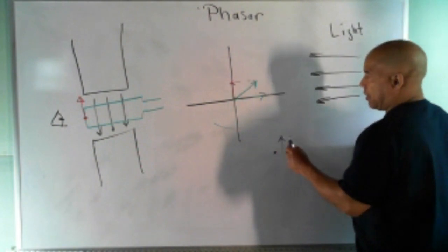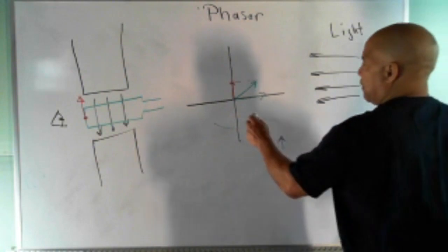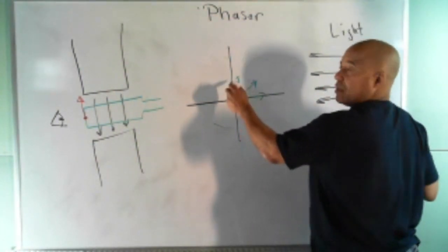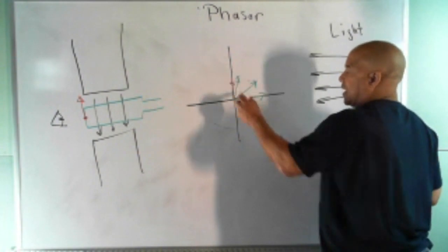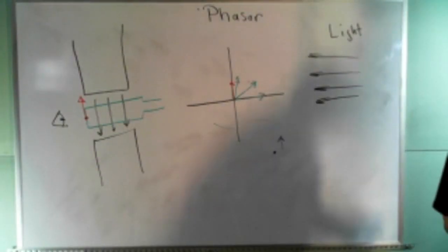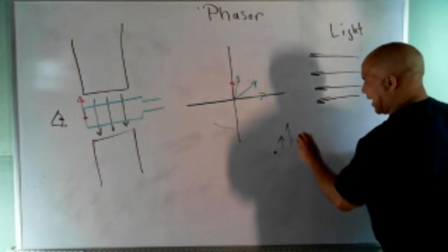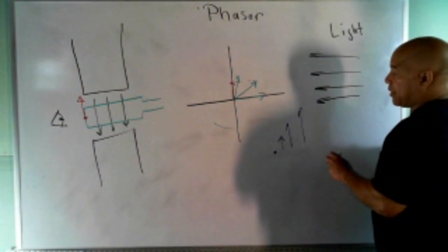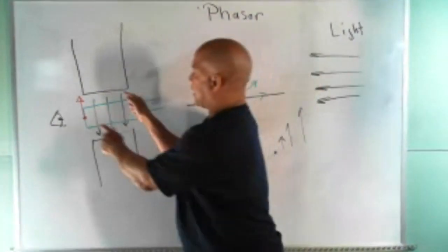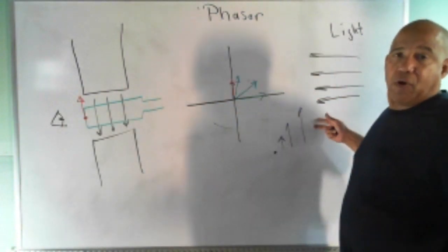Every time the coil moves and gets closer to 90, the shadow is going to grow. So at 90 degrees, the shadow and the arrow are exactly the same height. So it grows, and at 90 degrees it's like that, which means the force is greater at 90 degrees because I'm cutting more flux, which means the voltage and current produced is going to be more.